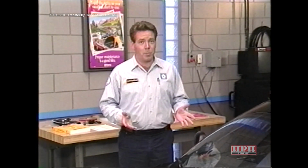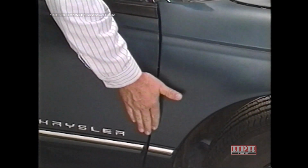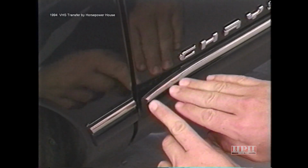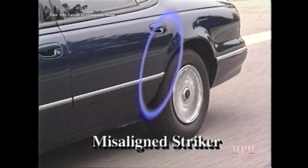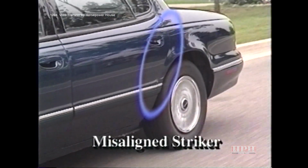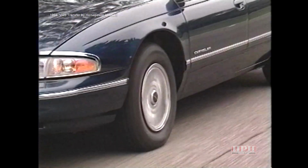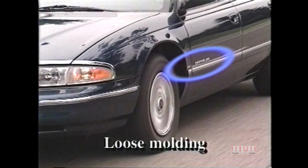Although we as technicians can't do anything about design, we can do something about protruding components and loose parts. Be on the lookout for such things as the front edges of the doors set out from the body surface, and loose, torn, or distorted components, which may result in turbulence. Turbulence is sometimes characterized by a low pitch or deep sound caused by a component disturbing smooth airflow. A flutter or buzzing sound is also used to describe turbulence. It is most often an external concern and is usually caused by a loose trim piece or molding.